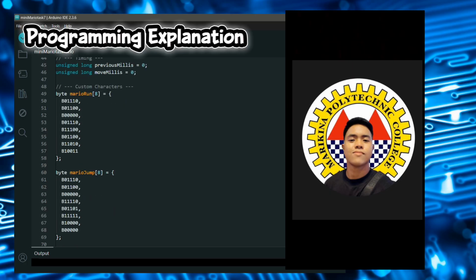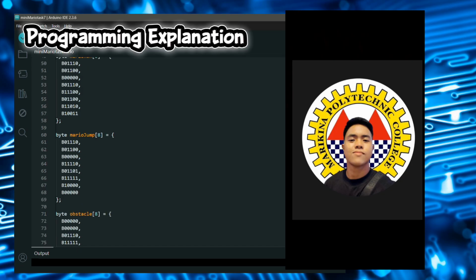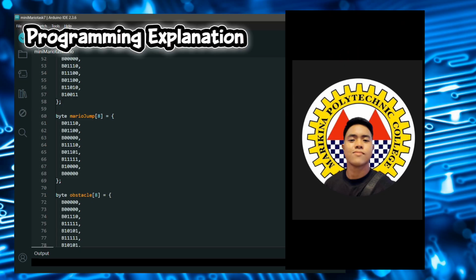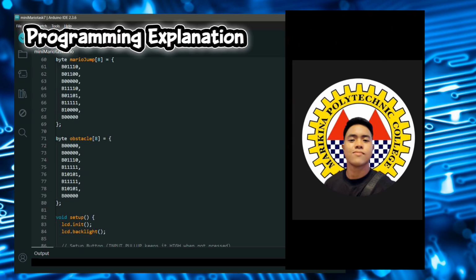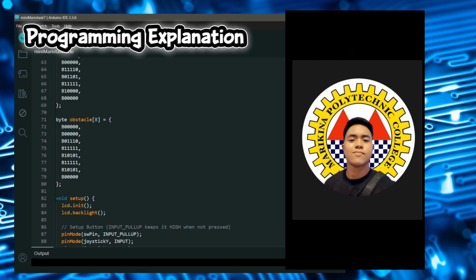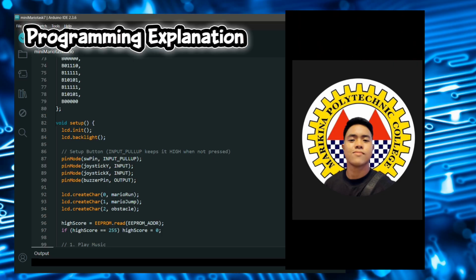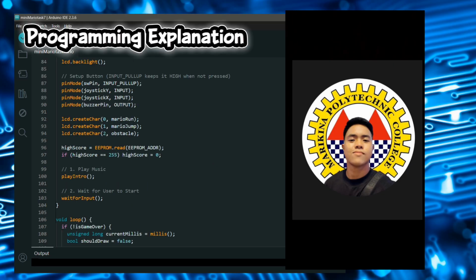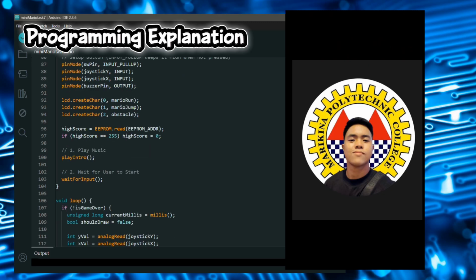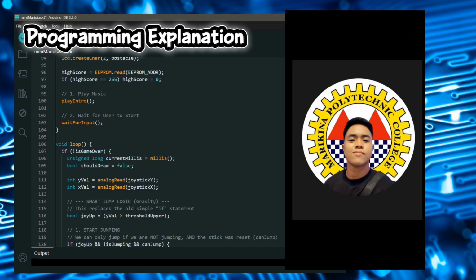Moving to the main loop, responsiveness is the key. Instead of using the standard delay function, which pauses the whole system, we use millis. This creates a non-blocking timer. It compares current millis against previous millis. This allows the game to move the obstacle at a set speed while simultaneously listening for player input instantly. This prevents the controls from feeling laggy.